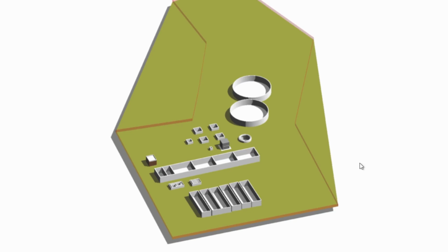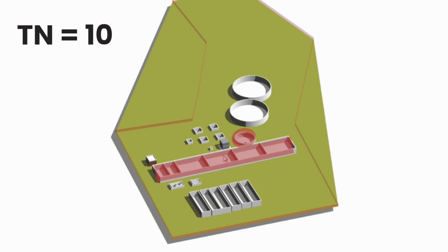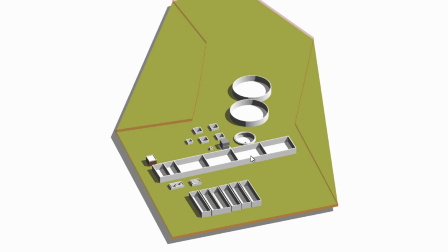The engineers first look at how the plant layout and assets would change. The biggest impact will be to the reactor chain and secondary clarifier. When the TN limit is 20, we see comparatively smaller reactors and a smaller secondary clarifier on the site. As the TN limit gets lower, reactor volume must increase and the size of the secondary clarifier increases as well. This will clearly impact the amount of space on the site, but it will also be reflected in the bill of quantities that TDG creates for each design.